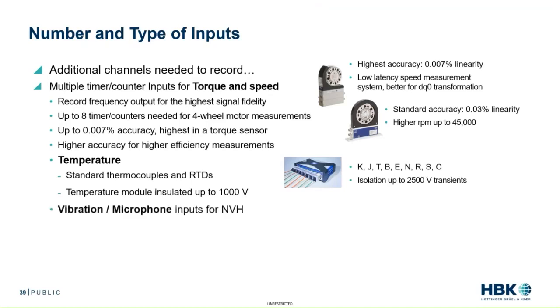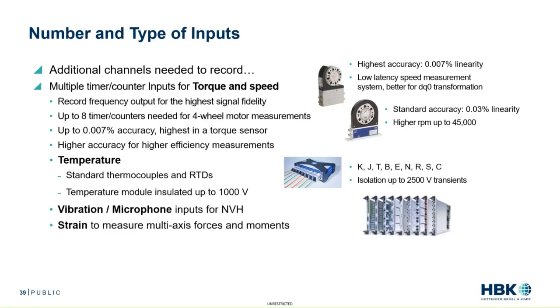Maybe you need to make some vibration measurements, microphone measurements for NVH analysis. So depending on the type of signals that you need to record, you want to make sure that your system has a variety of options to record those signals. For a modular system, you can see here, you could have a number of different cards that you would choose from depending on the signals that you need to record.